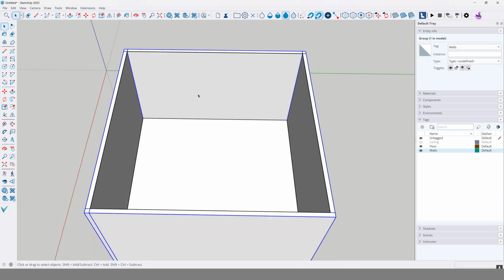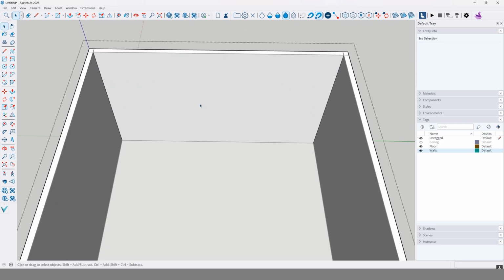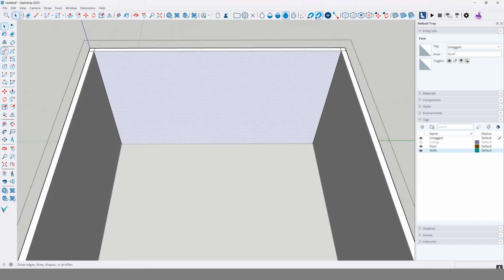So let's assume we want to add a door in on this wall here. We double click to open the group and we're within the wall that we want to add the door onto. Now, for the assumption of this, I'm going to say that the door is 2.1 meters, and let's just say it's 200 mm is where the door starts. So 200 in, here is your point, 100 up, and it's going to be, let's say, 750 across, 750 and